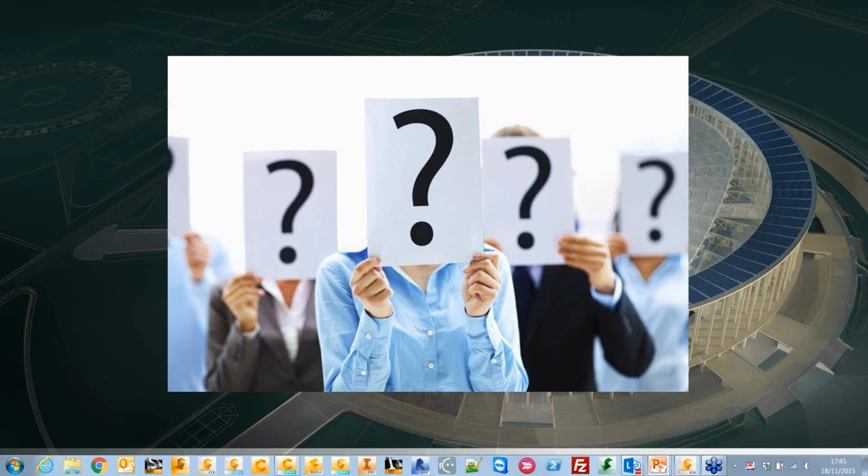Hey Todd, just to look at some of the questions that we have. One is if we have more than one fluid, say a heat exchanger with air and water, the summary file doesn't differentiate the mass and energy balance between the two. Is this correct? Right, that's what I was saying initially: you'd want to bookmark which ones are your water and which ones are your air, to make sure that your mass balance is correct for each of those flow paths.